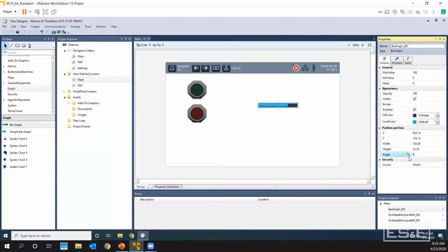Here you have an angle. So you can change this to any angle, but I want mine to fill starting from the bottom moving up, which would be 270 degrees. If I put 90, which most people would think, it turns it with the base being left up. So that's why I did 270, turning it. So now it turned the base and it went a full 3/4 of a circle and now points out.